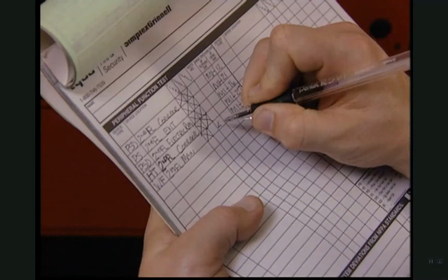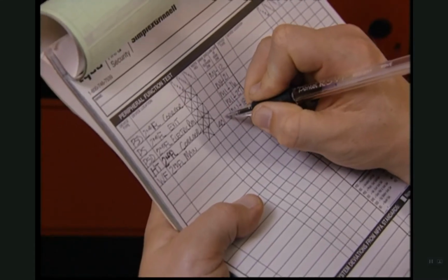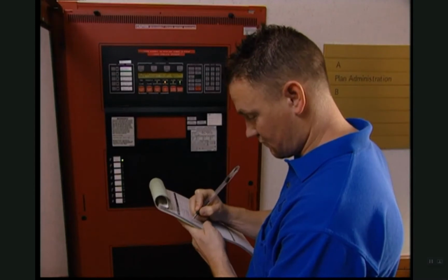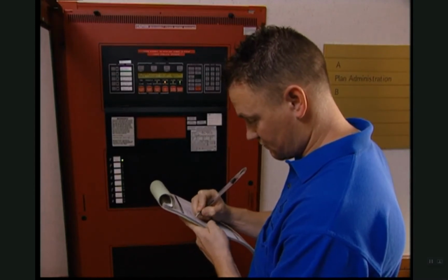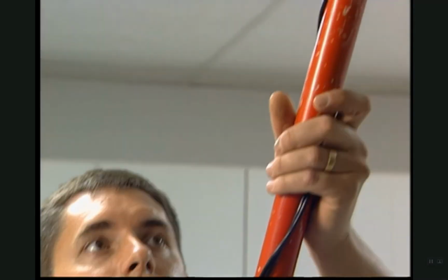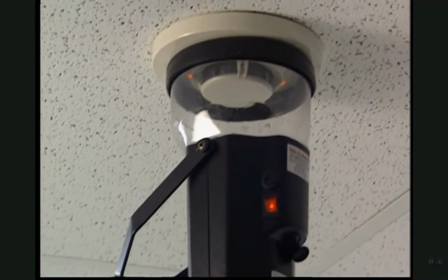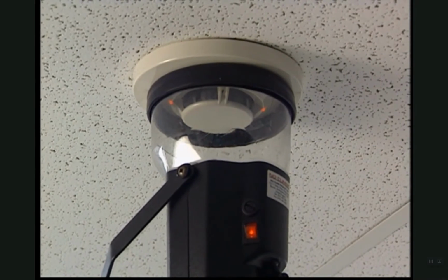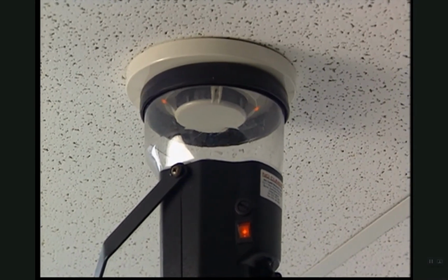Keep a record of every component disabled, and use this as a checklist for restoring all components. There have been cases when disabled alarm systems were never restored to service, or only partially restored. Oversights like this have led to property damage, injuries, and deaths.